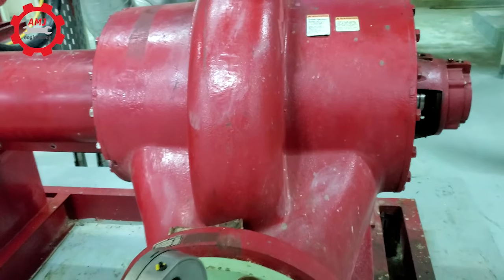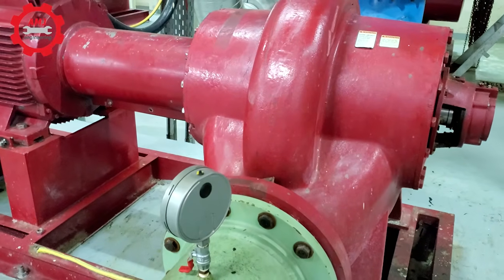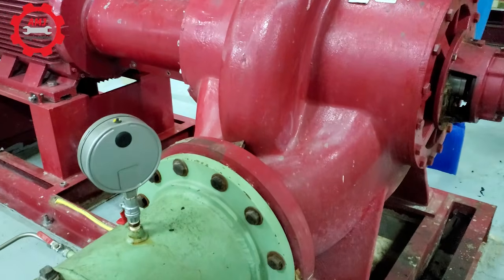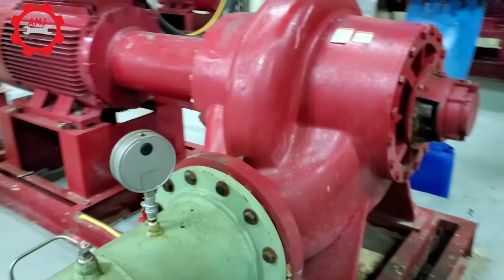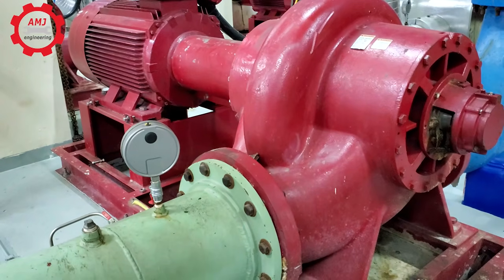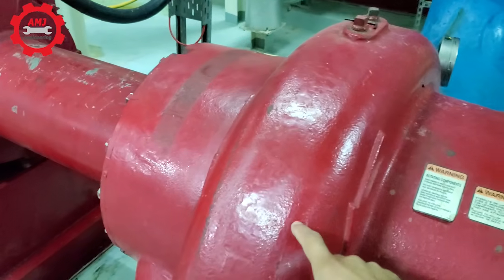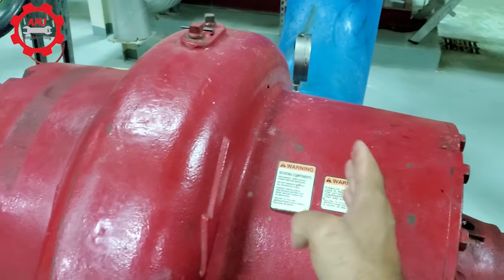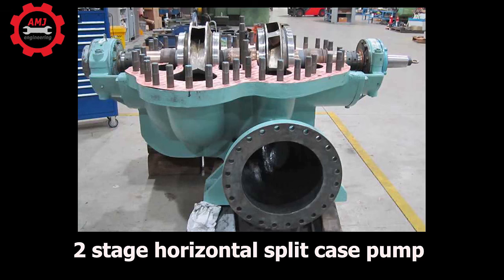Using double suction reduces the risk of hydraulic imbalance. The reduction of hydraulic imbalance is one of the reasons why double suction split-case pumps are preferred over single suction. Split-case pumps may have one impeller for single-stage operation or may have multiple impellers for multi-stage operation. Multiple impellers provide increased available head within a single pump.